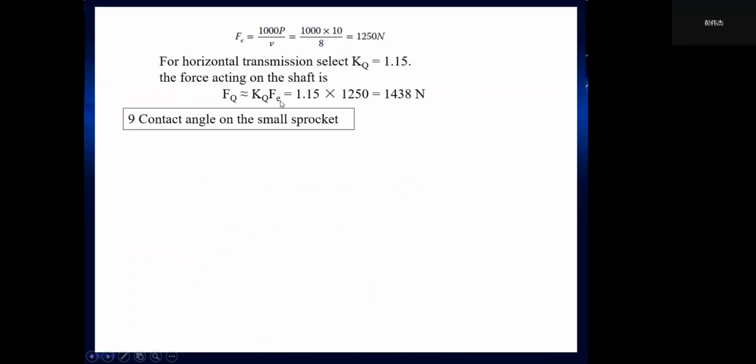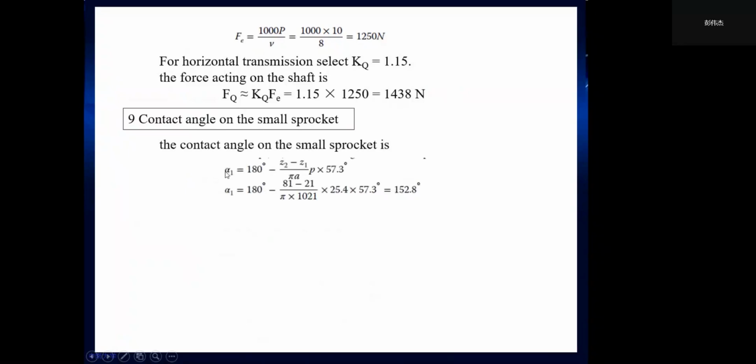We calculate Fe, the effective force, and use this to calculate the force on the shaft. Then the contact angle can be calculated with this formula. It should be larger than 120 degrees. It satisfies that, so the design is acceptable.